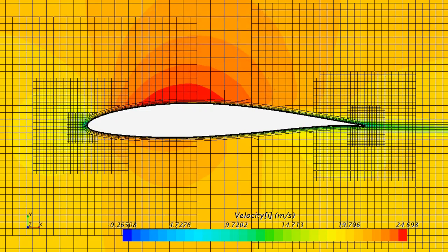Use of wall functions for the K-omega SST turbulence model rather than integrating to the wall can be appropriate depending on several factors, including the desired accuracy, the relative importance of skin friction drag, the importance of transition, and the existence or importance of separation and reattachment on smooth boundaries.